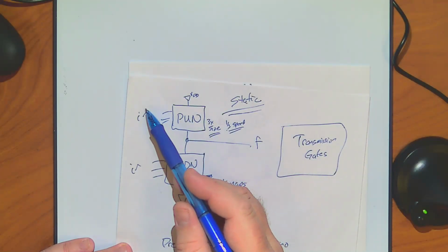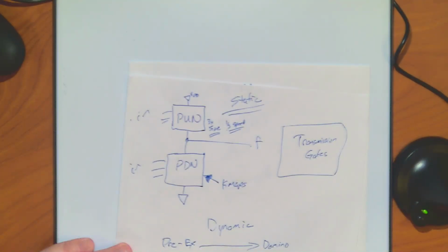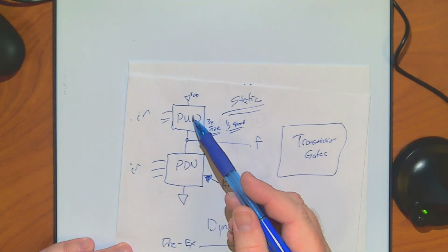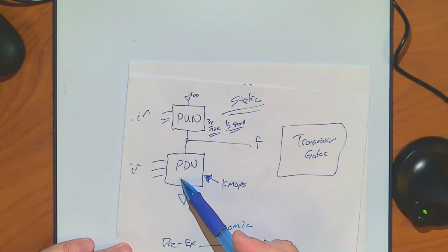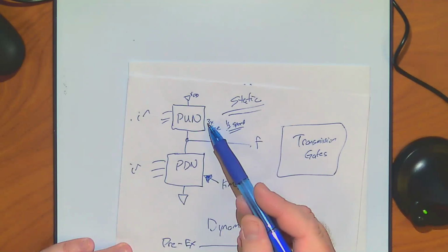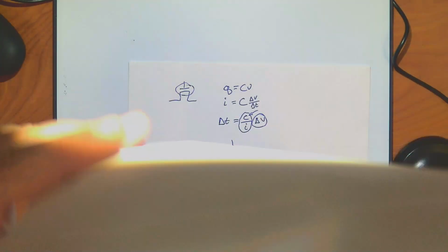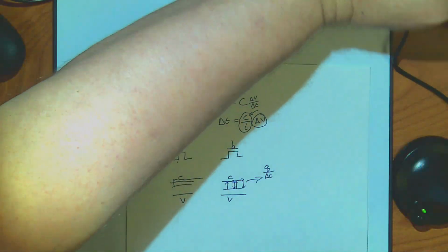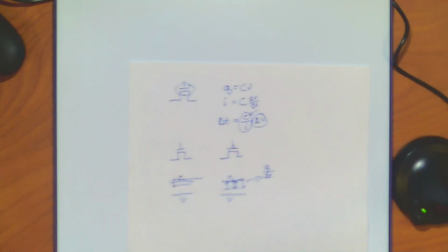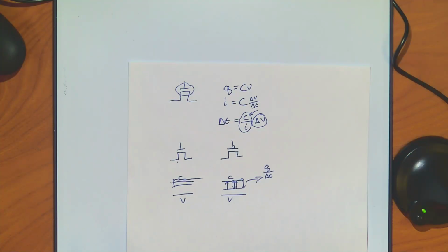And if you remember, for every input, there's roughly one transistor. So if I have n inputs, there's n transistors up here, n transistors down there. And this is 3/4 of my area. So if I can get rid of this, it'll be fast and small. Right there, that observation is completely the idea behind dynamic logic. Get rid of the pull-up network. Now, the only problem with this is that your pull-up network supplies power.